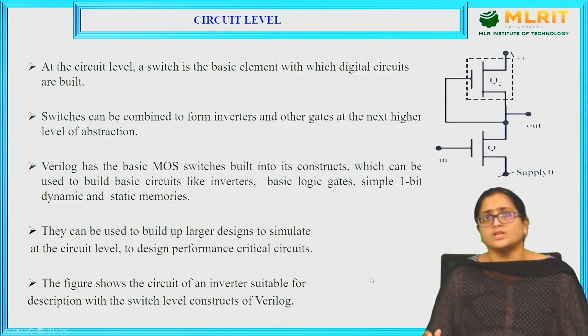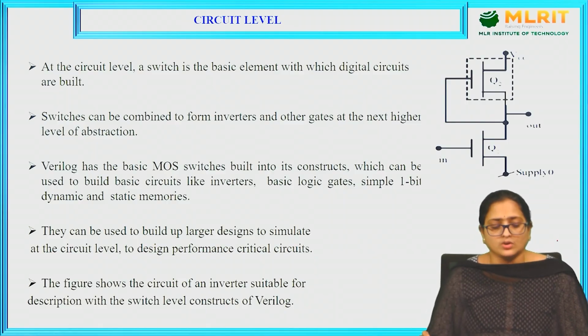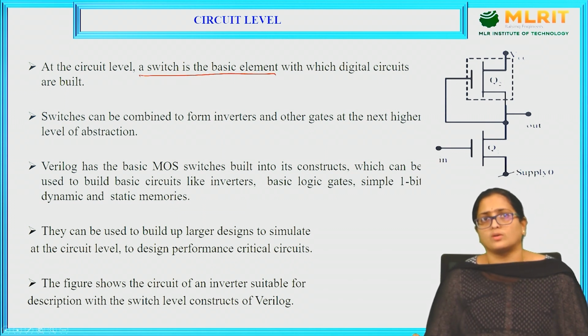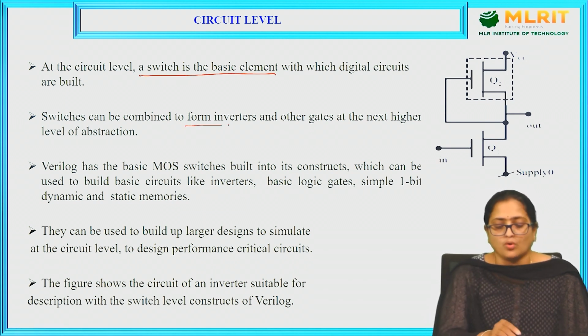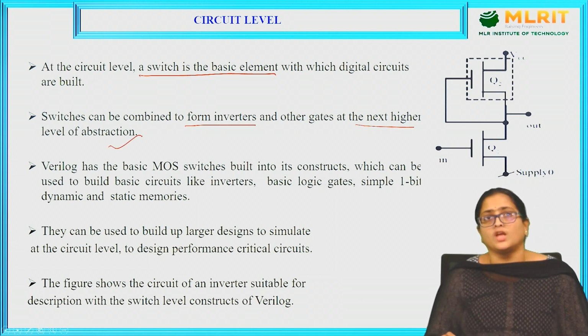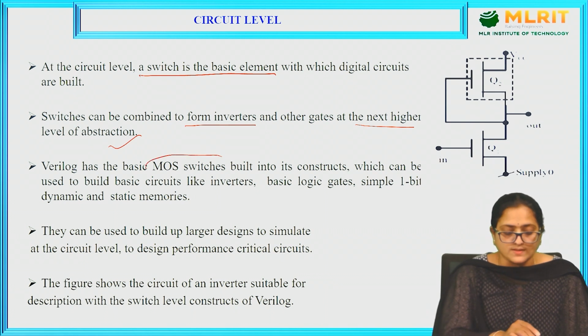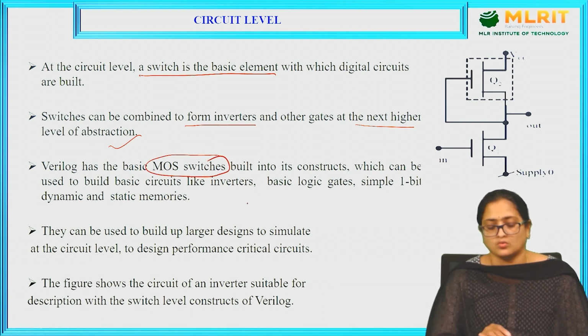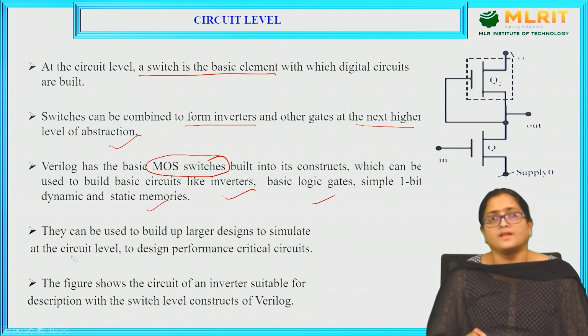The fourth one is circuit level designing. At circuit level, a switch is a basic element with which digital circuits are built. Switches can be combined to form an inverter and other gates at the next higher level of abstraction. Verilog has a basic MOS switch built into its constructions, which can be used to build basic circuits like inverters, logic gates, 1-bit dynamic and static memories. They can be used to build a larger design to simulate at circuit level and to design performance critical circuits.